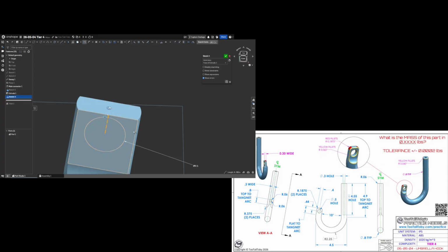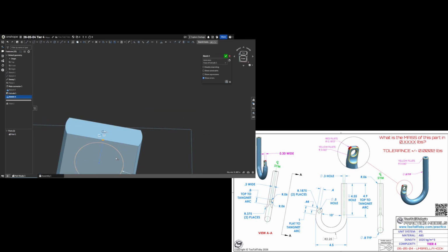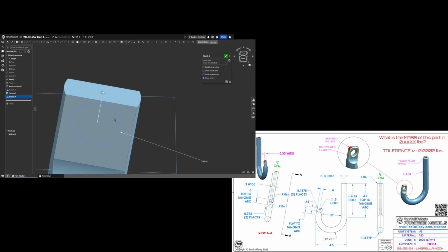And we're gonna make this and that parallel, which is B. Okay. Now we're gonna make this and the midpoint of that coincident. There we go. Now all we're missing is where it is up and down, which is 0.44. Easy enough. Actually, the line is 0.44.